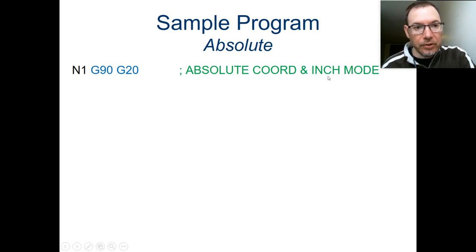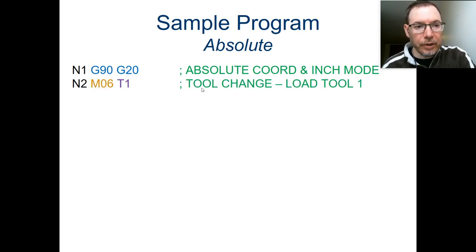So in this case, we're using inches. You could do millimeters as well. I can't remember the code off the top of my head. I think it's G21, but there is a different code for millimeters. We're going to stick with inches for right now, but you can definitely use millimeter code as well.